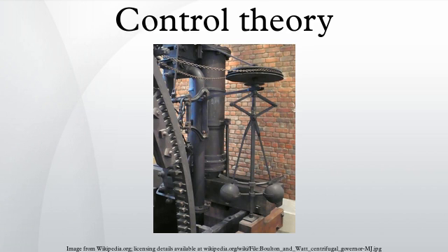Classical control theory. To overcome the limitations of the open-loop controller, control theory introduces feedback. A closed-loop controller uses feedback to control states or outputs of a dynamical system. Its name comes from the information path in the system. Process inputs have an effect on the process outputs, which is measured with sensors and processed by the controller. The result is fed back as input to the process, closing the loop.